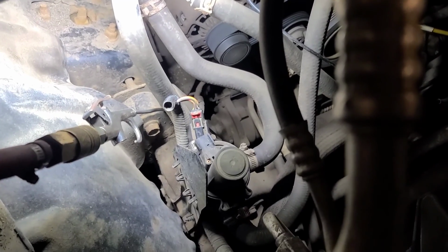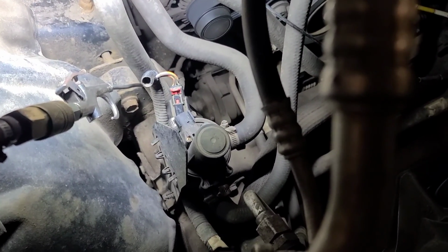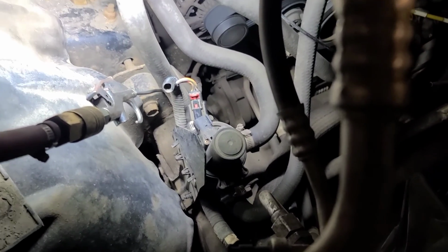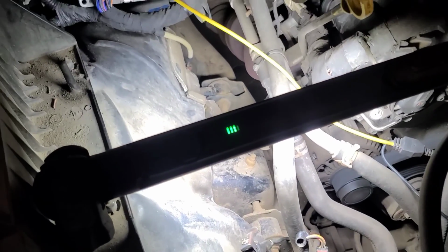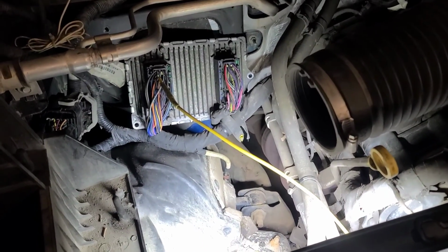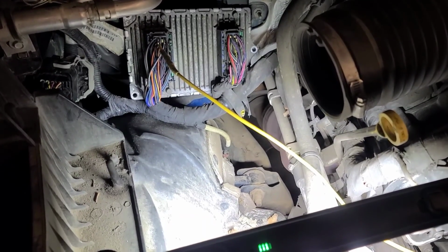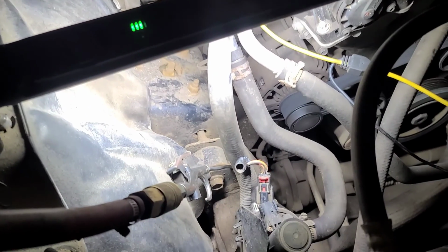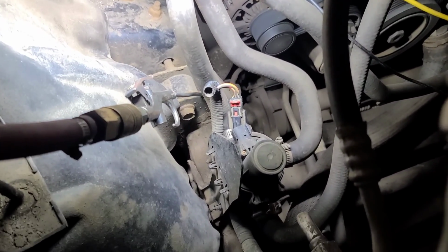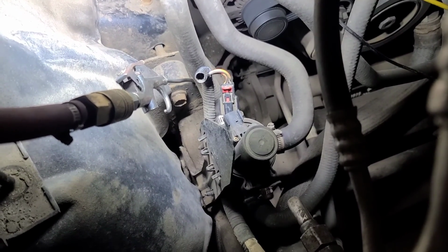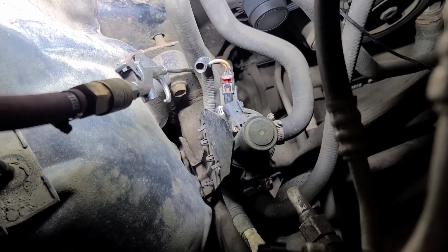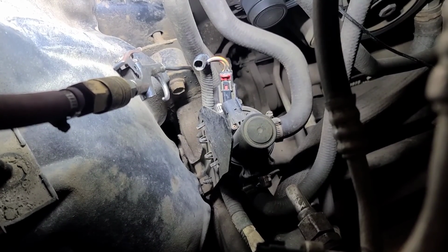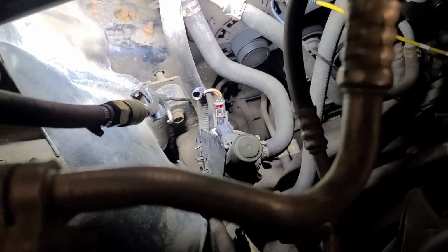I forgot about the pull-up resistor in the position sensor circuits and pressure sensor circuits, so that kind of led me astray. And the numbering sequences on these ECM connectors are confusing at best, and it's very hard to see the pin numbers. So I'm going to leave this disconnected and take it for a road test with it unplugged. I'm not sure what effect that has on, that's for the heater anyways. Yeah, I think that bypasses the heater when it's cold or when the AC's on. It's just over-engineered for no reason, to be totally honest with you.